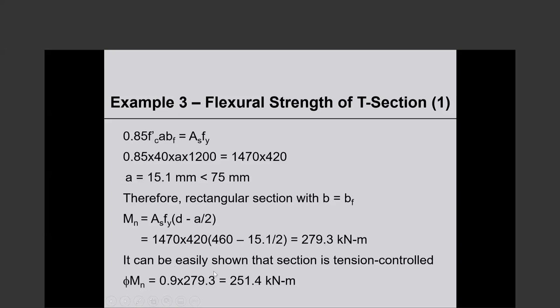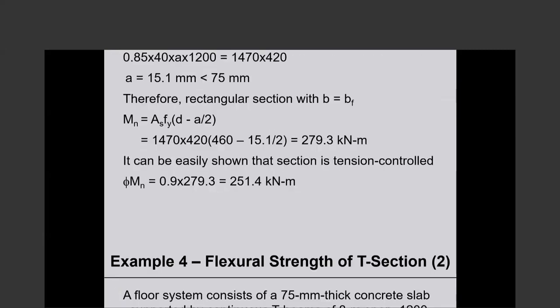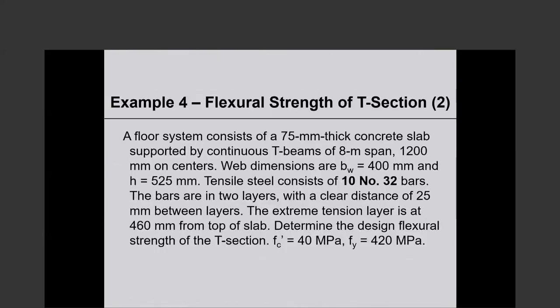It can be easily shown that the section is tension controlled, which makes the design moment strength 90% of the 279.3, and that's 251.4 kilonewton meters. Okay.